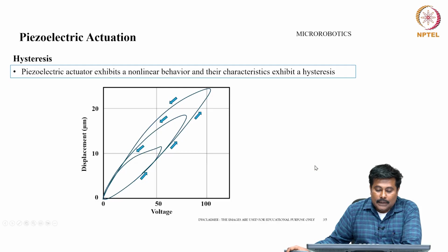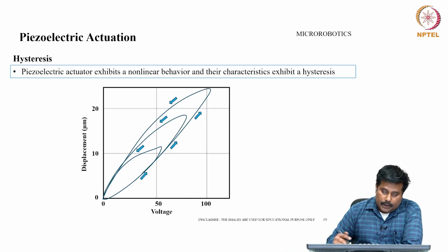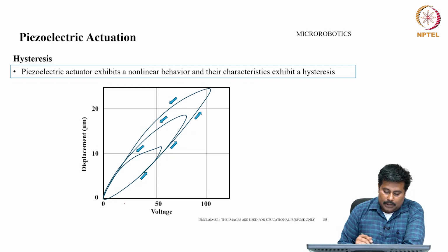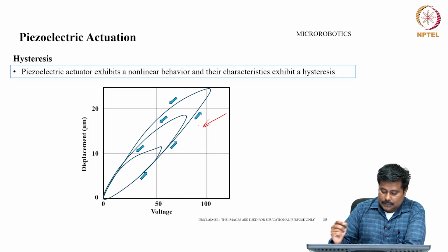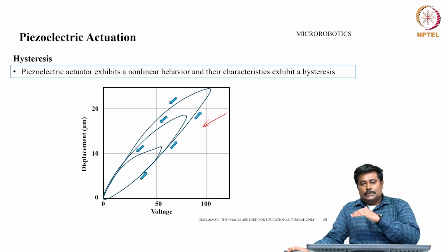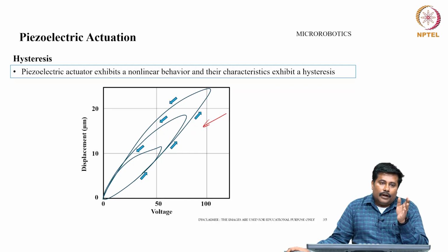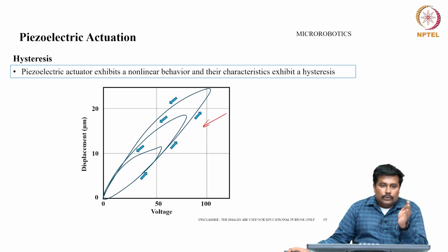Now, one of the major issues with reference to piezoelectric structures is that these piezoelectric actuators exhibit a kind of nonlinear behavior, and their characteristics exhibit hysteresis. When we plot a curve of displacement versus voltage, we can easily observe a characteristic which leads to hysteresis in the process. This hysteresis is a kind of defect which impacts the overall performance in the usage of these piezoelectric structures for different functional applications.